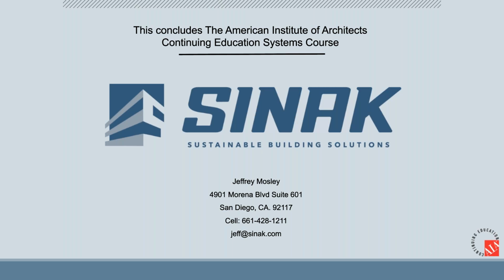If I'm specifying this new category of curing agent, I would put it in Division 3 because it is a curing agent that's applied at the time of concrete placement. But when I do my master spec reviews, I also include it in Division 9 because Division 9 has the requirements for moisture for flooring. That way you get 9 and 3 talking to one another at pre-construction so that you avoid finger pointing and delays and arguing later in the process. It's much more cost effective to address it early than to try to figure out who's responsible later. This also prevents you from tapping into contingency money that you get to take home if you're a general if you don't use it.